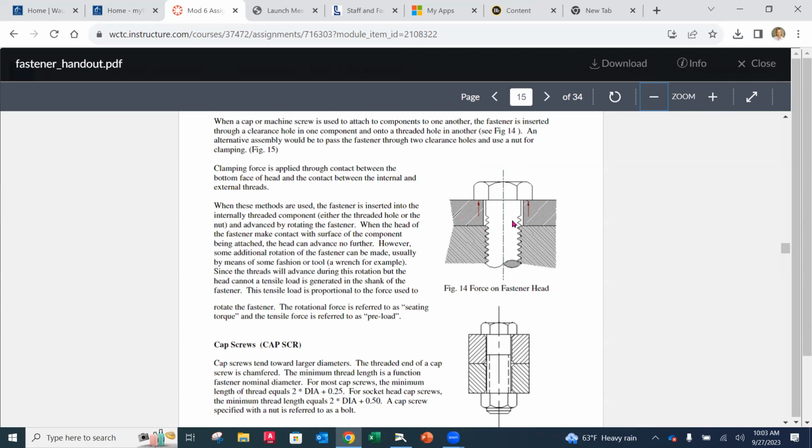So notice that there's a gap, right? And so that way the fastener can go through, but then in the piece where we're adding the cover to it, notice that now we have threaded holes. This is called a fixed fastener type of an assembly, where we have the clearance on just one part and we thread into the other.